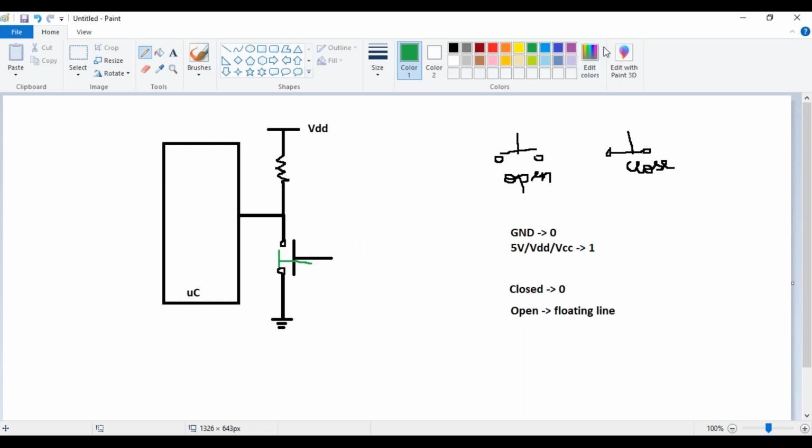That depends on the pin of the microcontroller. Some of the pins of the microcontroller you select will have an internal pull up or pull down already available. But if it is not there, you will have to add it externally. It completely depends on the microcontroller you have selected. Assuming it doesn't have a pull up or a pull down circuit, I'm going to add it externally.